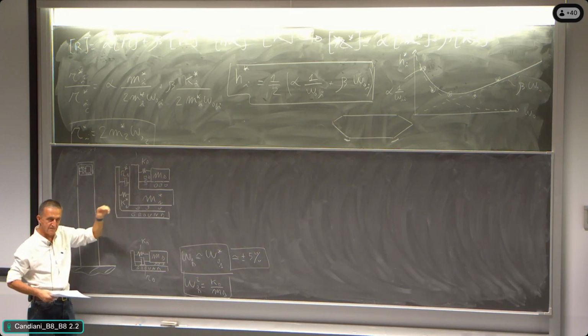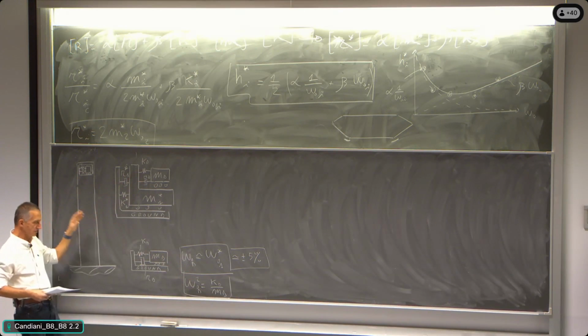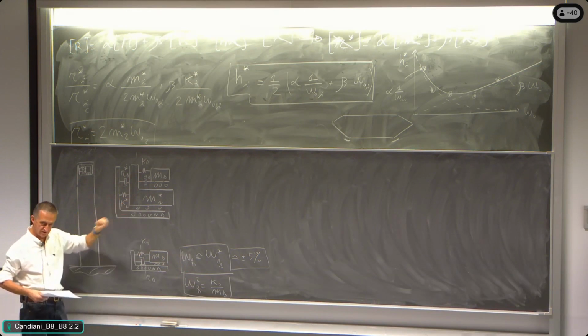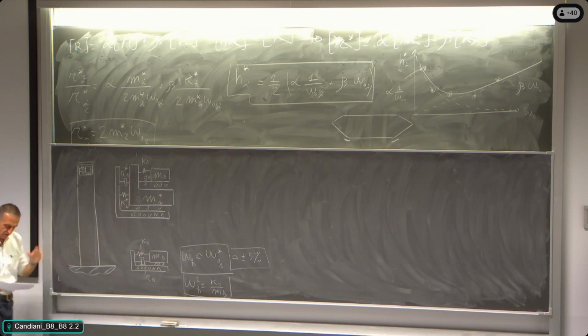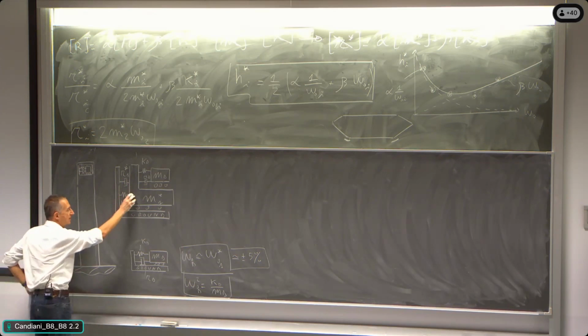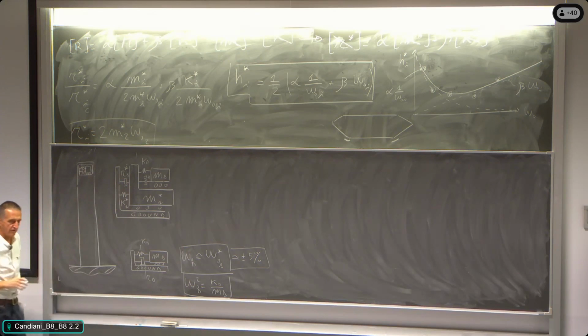And so the tuned mass damper will move a lot when the system is moving along the first natural frequency, all right? And it will dissipate. So this is the way in which the system is working. All right, first of all, I would like you to be confident with the model representation of the problem,